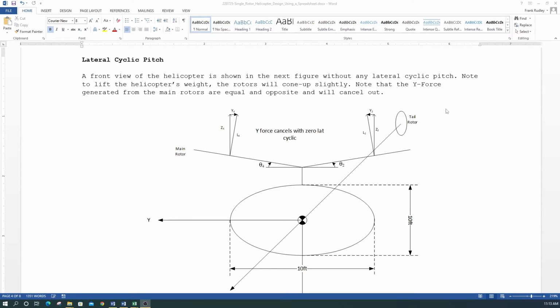So as this rotor system moves, the blades are exchanging these forces. So you have to visualize that. Like what's shown in this figure, it's true for an instant in time where blade 2 is out here at the 90-degree position and blade 4 is at the 270-degree position, but these blades are constantly moving around. So say blade 1 turns into this position, and so the y1 force at that point would cancel out the y3 force. But these vary in a sinusoidal motion as this blade system turns.